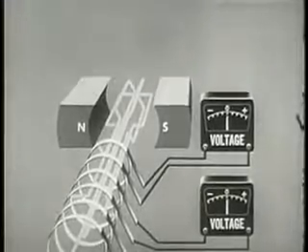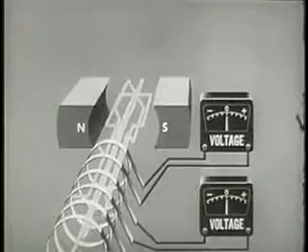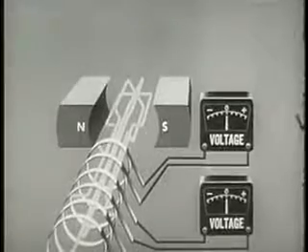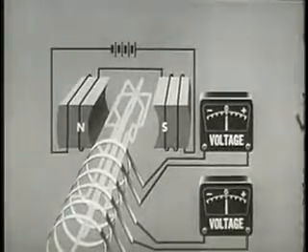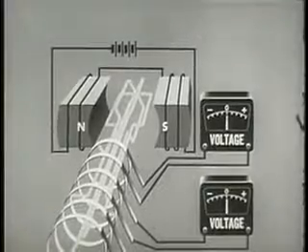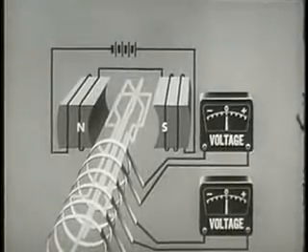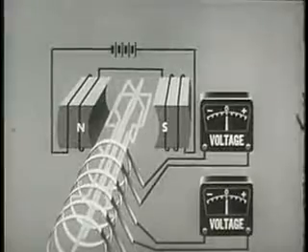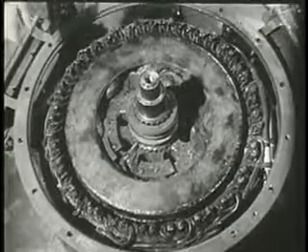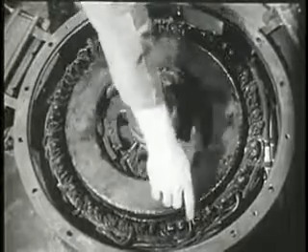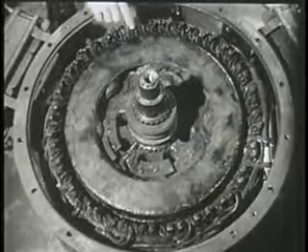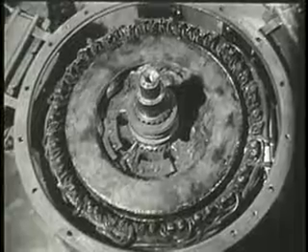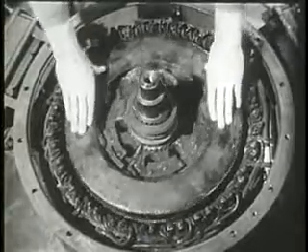Alternating current generators using electromagnetic fields, however, cannot be self-excited. DC is needed to excite the field. In practice, a small DC generator set in tandem with the main machine in one housing does this. Large AC generators are sometimes constructed with a stationary armature and a rotating field.